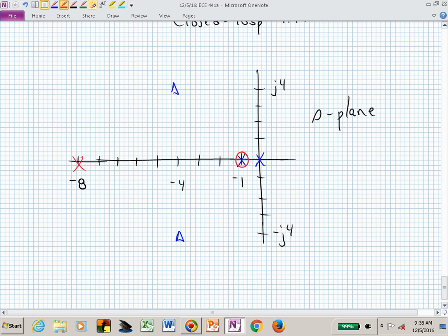And that's not right, is it? Are you counting? Are you kidding? There. It didn't look symmetric. Even though my diagram wasn't very accurate, it still didn't look symmetric. Now it looks better. So now we have this branch coming in there, this branch zipping through there. They break halfway between, which in this case is at -4. And we adjust the gain.